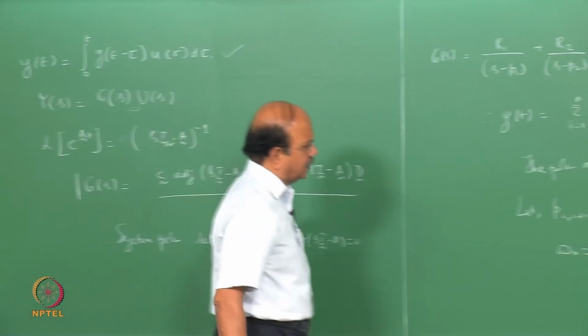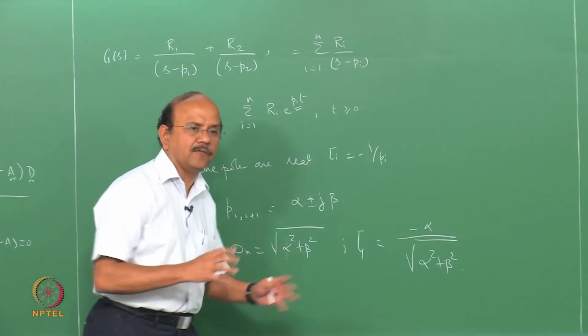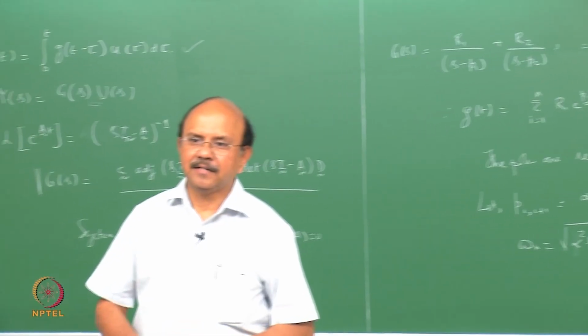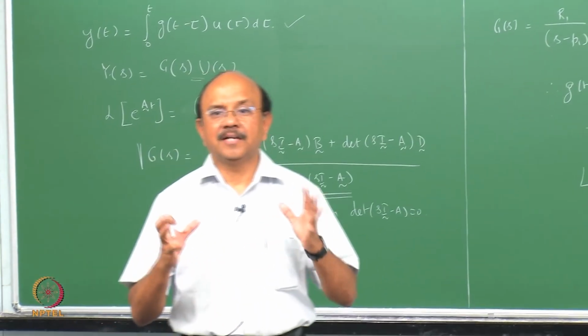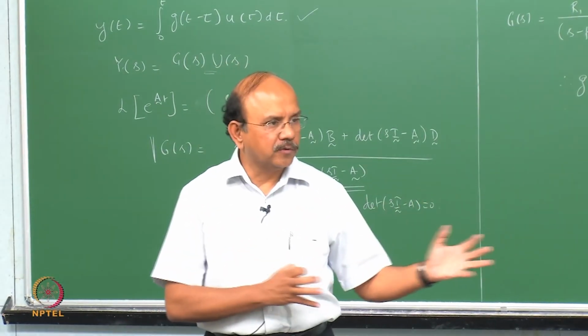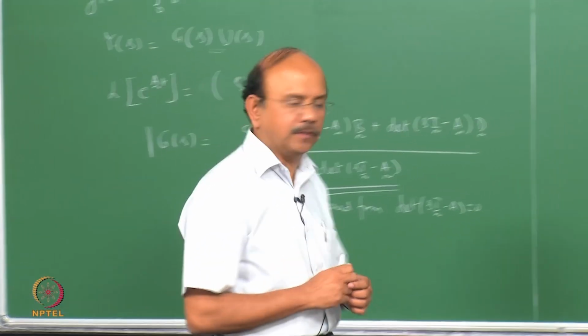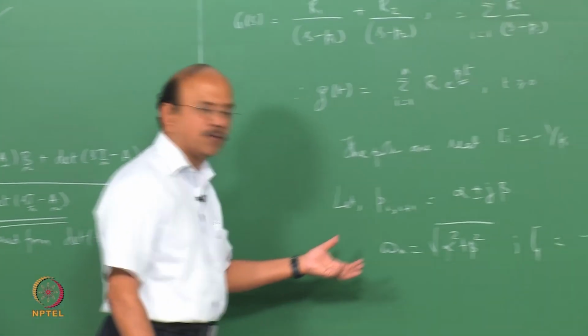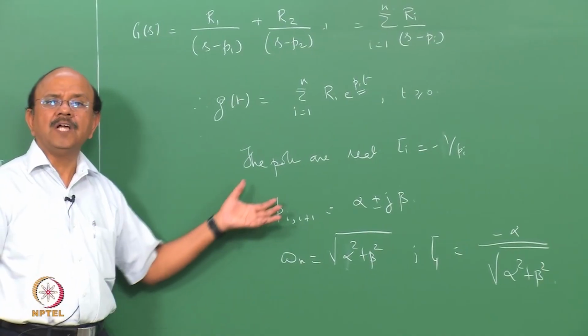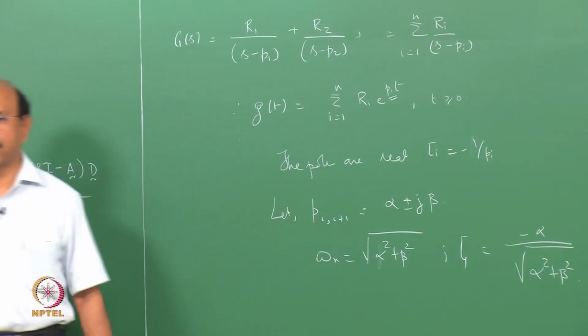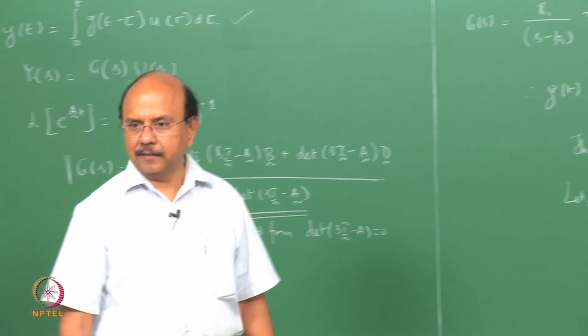One of the questions which people have, especially when they come from a vibration background, is that of the connection between the natural frequency and these poles. Okay, there's always a confusion as to what we mean by natural frequency and damping. In other words, the poles of the system are expressed in a slightly different fashion, as omega n and zeta.